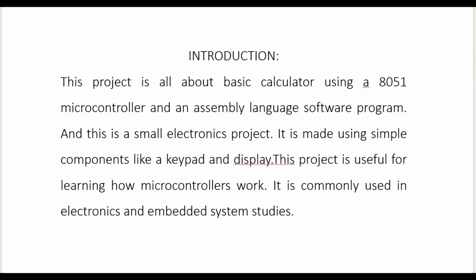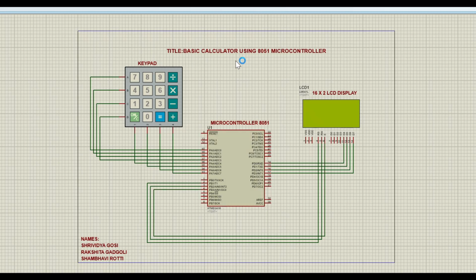Now I will show you the project. Basic calculator using 8051 microcontroller. The components consist of a keypad, the 8051 microcontroller and a 16 by 2 LCD display. Now we start the project by clicking the simulation button. After clicking the simulation button, the LCD displays "calculator please press on". For the operation, we need to press the on button on the keypad.